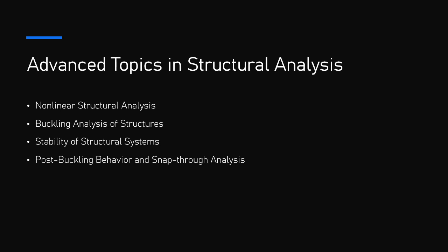4. Buckling and collapse analysis. Buckling analysis involves solving for the critical buckling load, which can be determined through methods like linear bifurcation analysis, nonlinear static analysis, or dynamic analysis, to account for time-dependent effects. Collapse analysis considers the entire load displacement path of a structure, particularly focusing on the post-buckling behavior. It includes load redistribution, plastic deformations, and the ultimate load capacity of the structure.